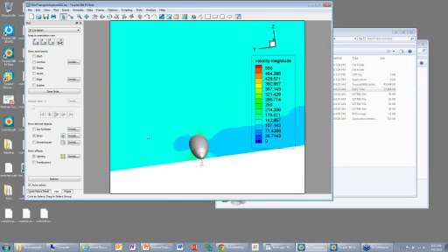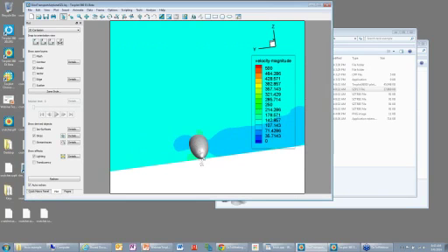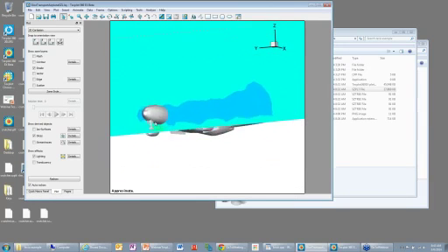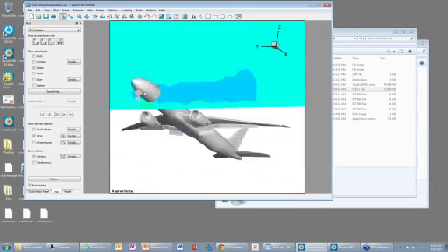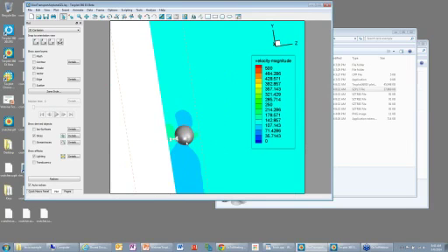Yeah, it's pretty significant, and I think David, or was it David or Kyle, had asked the question about performance. Under options, there's performance, and if you use approximate plots, basically what it does is grid decimation, which, as Scott pointed out, initially has to go through and do that decimation. But once you have it, when you rotate, you're actually rotating less data, and as a result it's extraordinarily snappy. Then it does the full redraw when you let go of the mouse. Yeah, when you let go of the mouse, it pulls the data in.